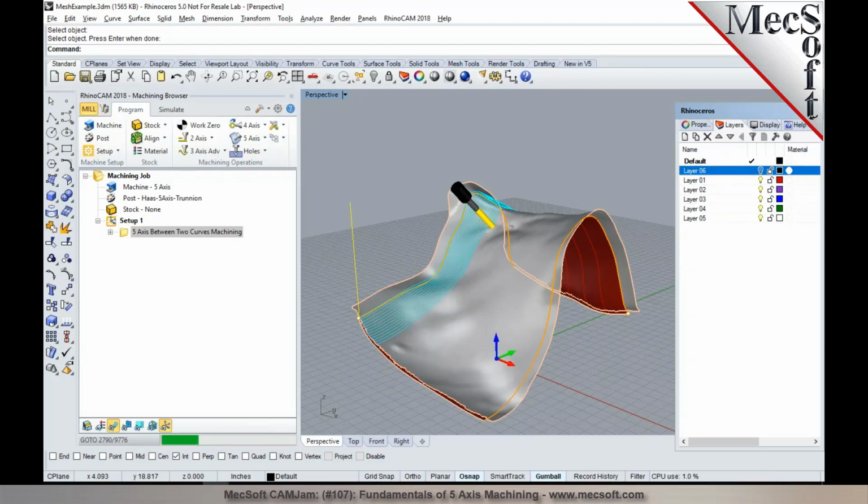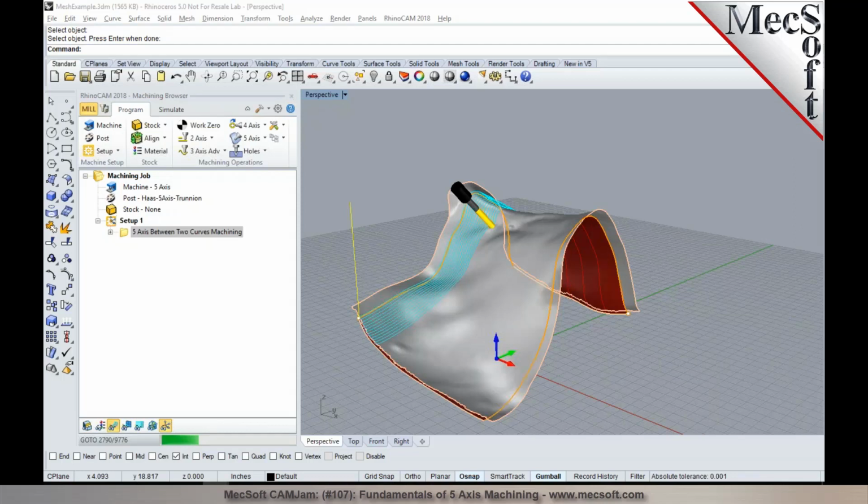Yeah, there was a question about error conditions. What happens if program position or orientation is unreachable by the machine tool? Maybe I can take that. So if there is something that we compute using the drive surface that the machine tool cannot reach because of the machine tool limits, there's a couple of things we try to do.